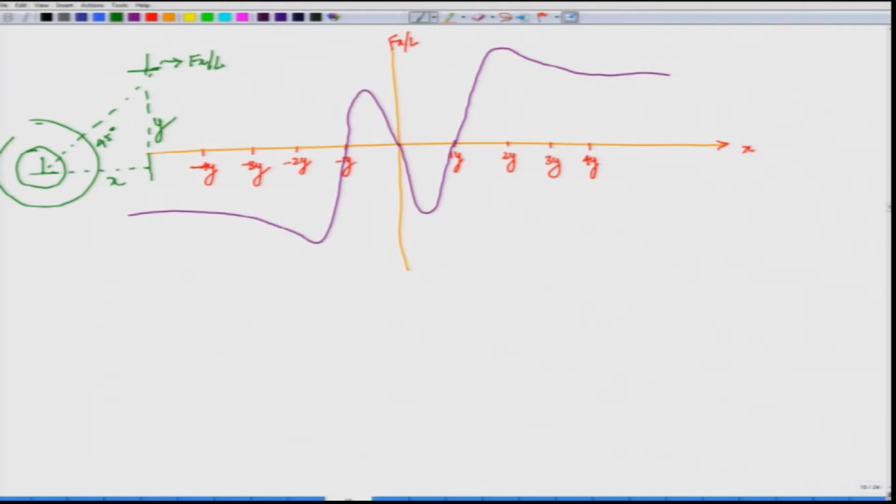So, what does that mean? If it is less than 0, meaning negative, if you have the dislocation somewhere over here, let me draw it with another color, it tends to move in the negative direction. So, it tends to move like this. If it is exactly at this position, then there is no force. If it is somewhere over here, it tends to move like this.